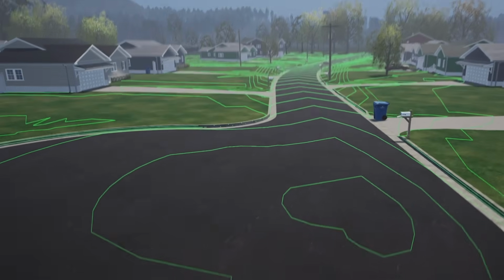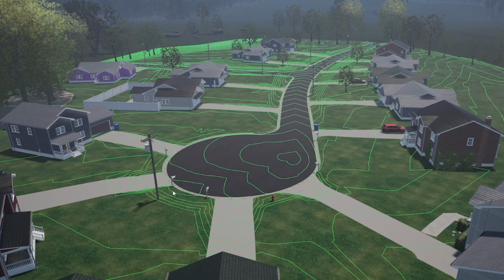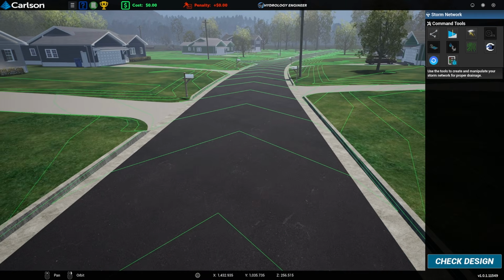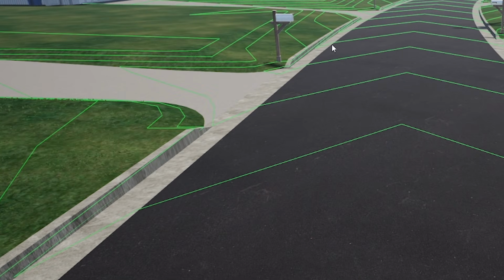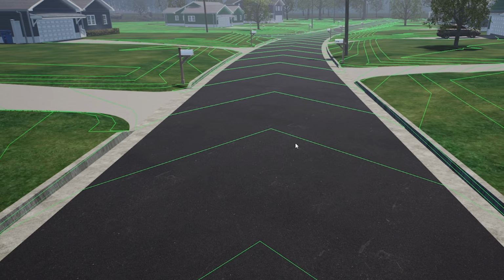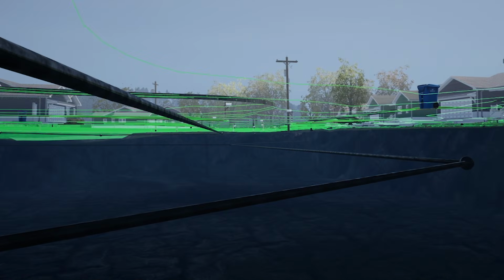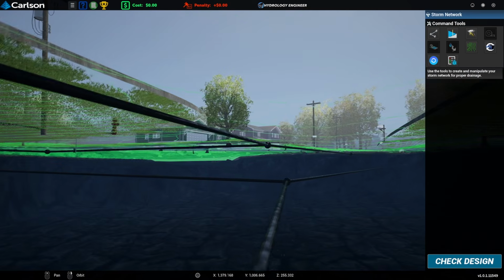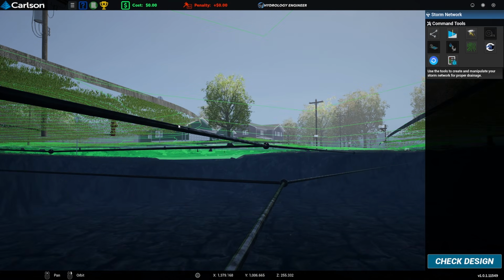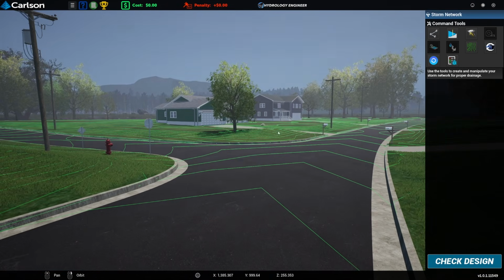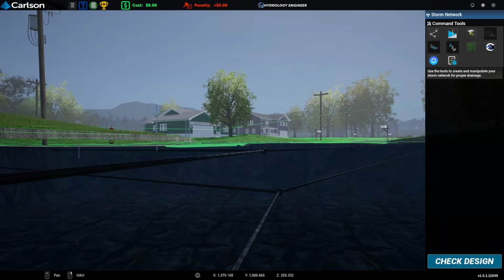You do get the odd occasion, say you are actually building a brand new housing estate like this, where you may build all of that stuff at once. And then you generally get quite a nice little setup where basically in the road, they say, right, the first meter on the left, that's reserved for drainage. The next meter is reserved for telephone wires, then gas, so basically everything's segmented and then you don't get any clashes. But most of the time it doesn't work like that because we're working with things that have been there for years and years. So it's all about trying to make your drainage flow downhill whilst dodging all of these services. Now it's worth noting we have been told that the higher ones, these are the water mains. So basically all of these houses, to get water to your taps, you have high pressure water mains.